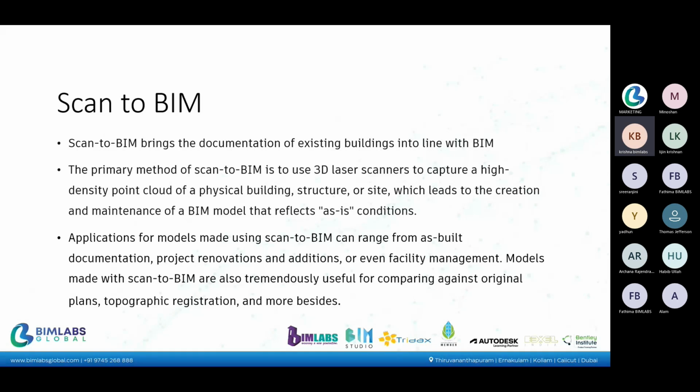After this laser scanning, the resulting survey data is called a point cloud. We can open it in the ReCap software, review it, or make any changes there, and then transfer this point cloud to Revit and redraw the plan. We will get the exact plan of that building.